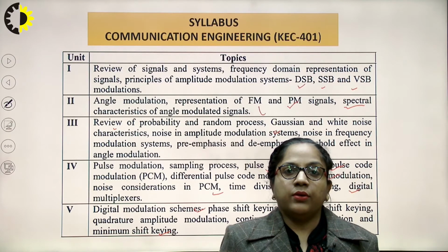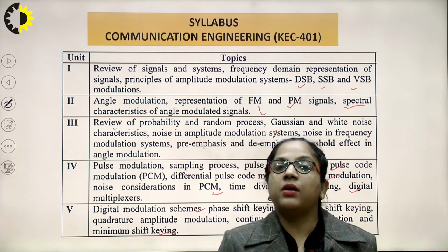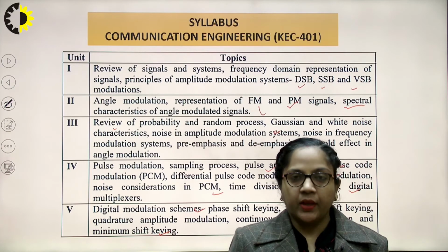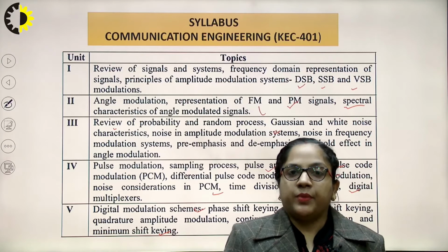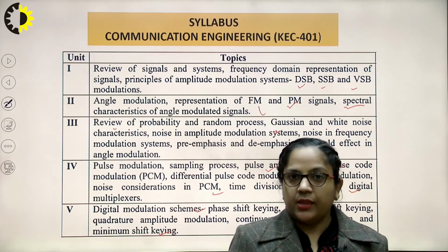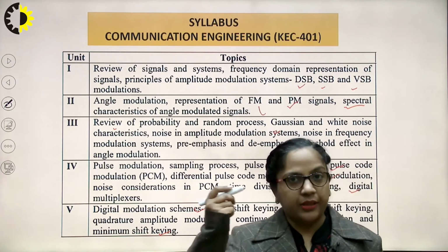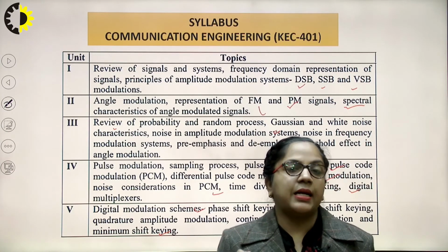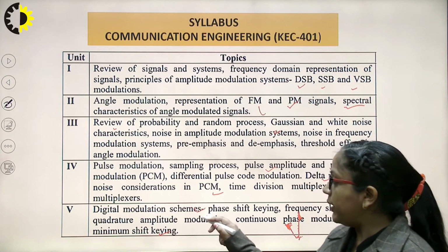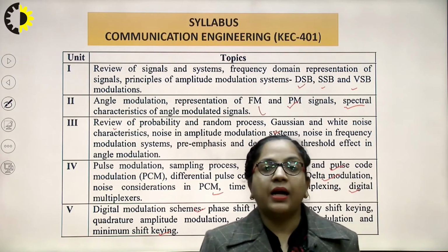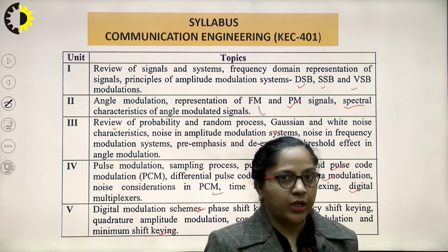This modulation process will be done with the help of a high frequency carrier signal. This carrier signal will have 3 main parameters, that is amplitude, phase and frequency. So we can basically categorize modulation schemes under these 3 parameters, that is amplitude, phase and frequency modulation. While performing digital modulation, we can have amplitude shift keying, phase shift keying and frequency shift keying to perform the modulation.